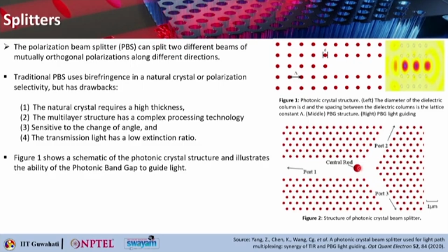So the light path had a suitable splitting ratio at the input and output, thereby satisfying the splitting and cycling requirements. When the large dielectric column is positioned at the center of the branch, the beam gets strongly reflected back, something like 85%, and it causes very low beam intensity at the output at port 2 and port 3.